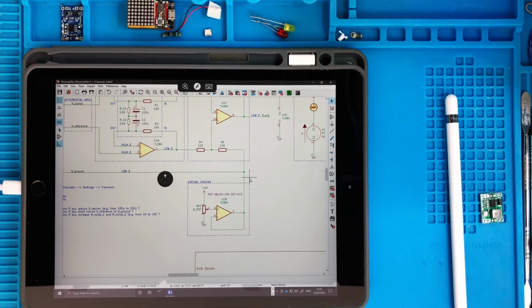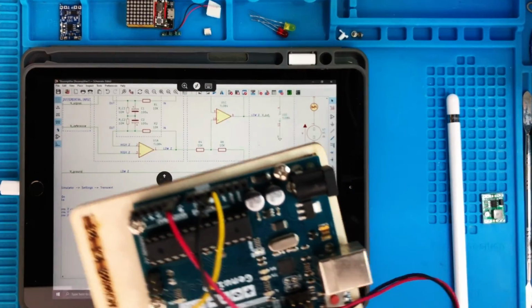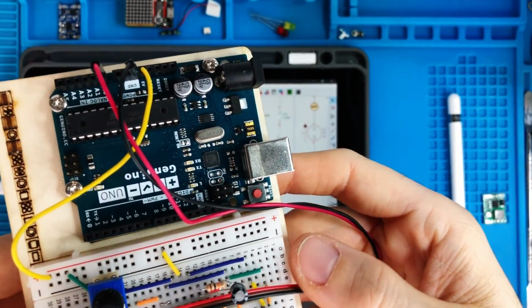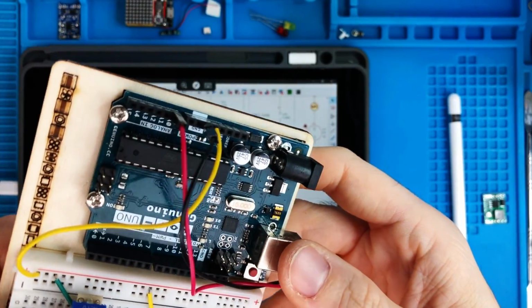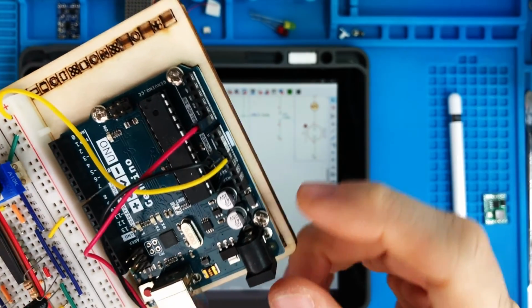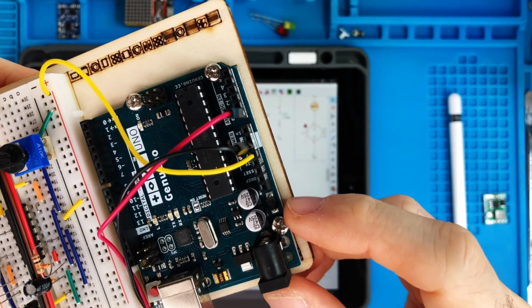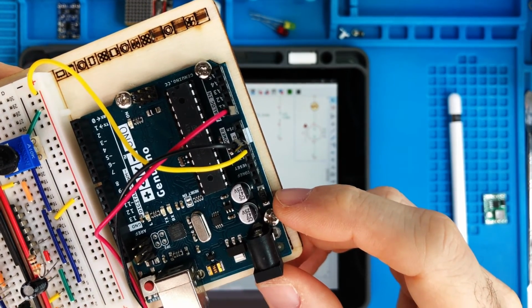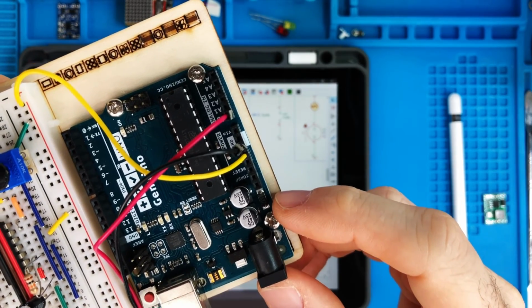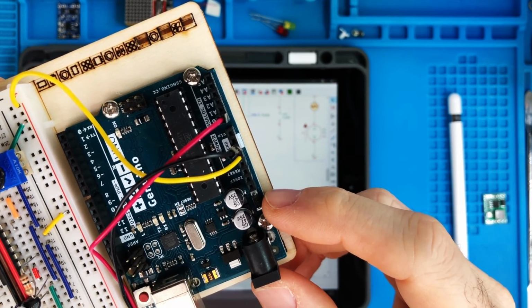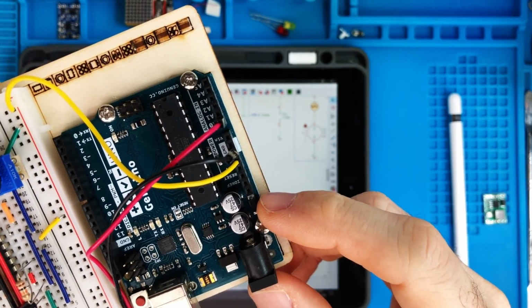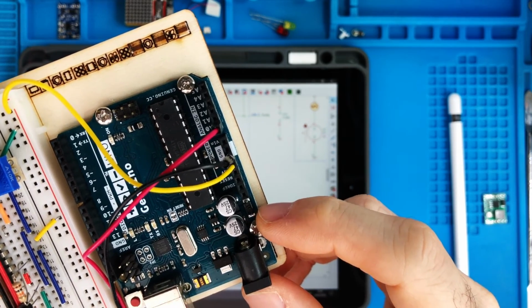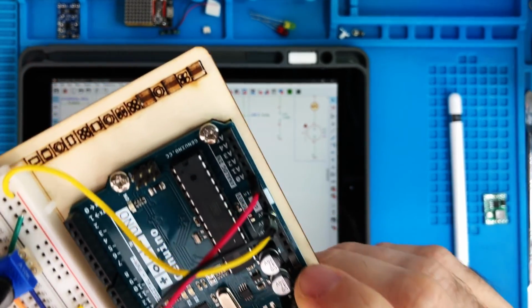So we don't have such a dual power supply, which basically means that we need to have 2 batteries here connected in series, but we have only 5 volts. So we need to find a way of having 2 voltages, one positive and one negative, with respect to the ground.